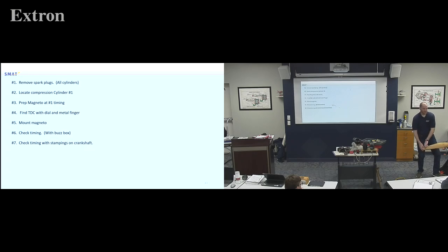Now I'm going to go backwards, and it's going to hit again. All right, so I hit the first time, I hit the second time. This should be the exact opposite side. So halfway between those two hits, you would say is either bottom center, or when I go to the next, it'll be top center is what I'll show you. So I had adjusted it to top center. Now I'm going to look at it and say, it says 80 degrees right now. There's a couple arguments on how I can adjust it from here.